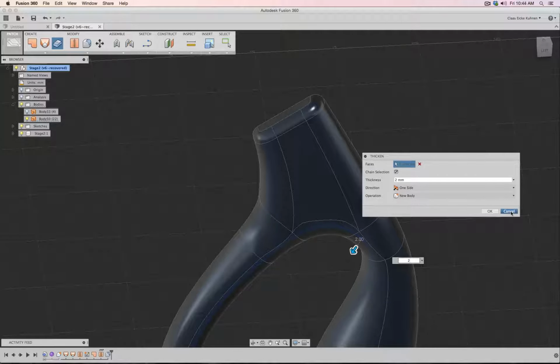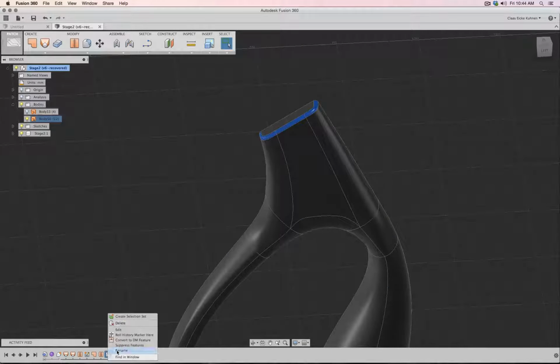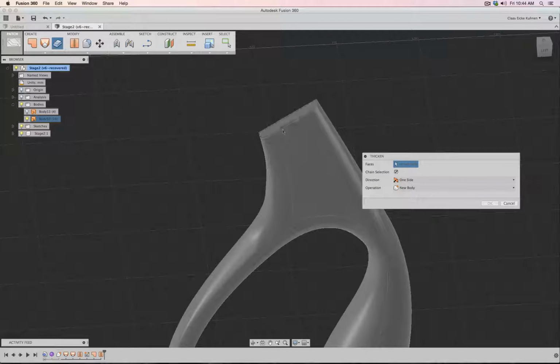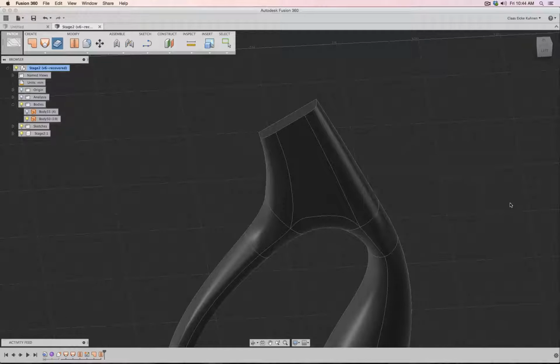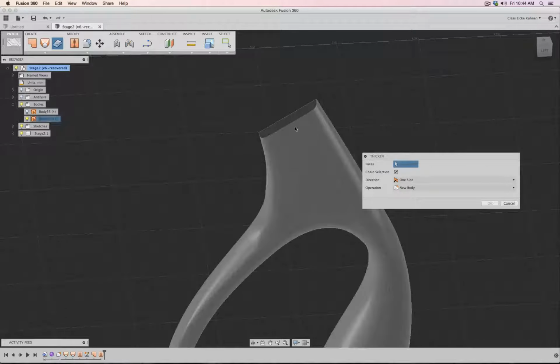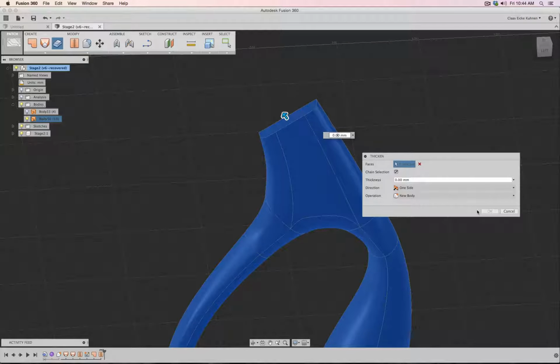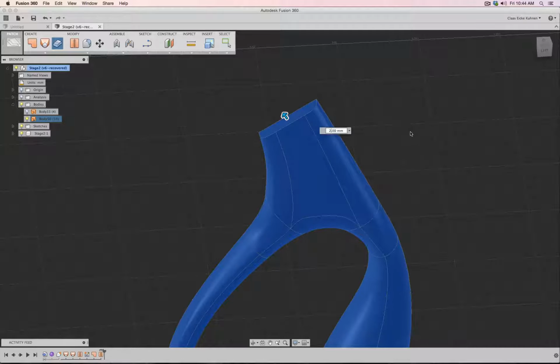And cancel, because that fillet is growing way too big. So I delete it and I just fillet that one. I'm going to fillet it afterwards, because I only need the fillet to be newly visible on the outside, so the A surface.